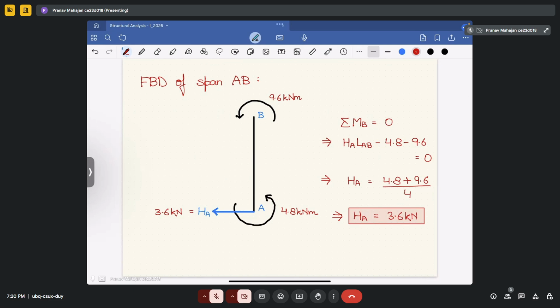We started with determining what are the different methods which come under the displacement method, or you can say stiffness method. In that, we started with finding out the values of rotations using compatibility equations at different points of the frame. Then we solved one derivation question to determine what will be the rotational stiffness when the far end condition is fixed.